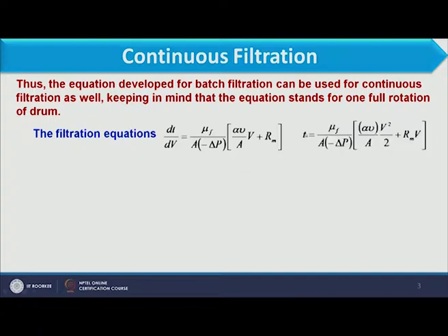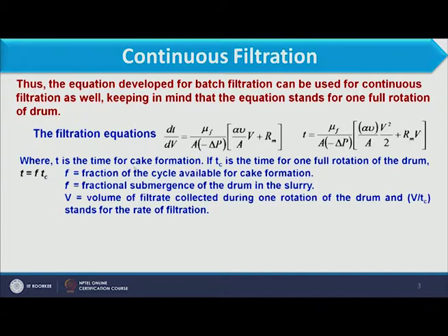When we integrate it, we get the time expression in terms of volume, where t is the time of cake formation and V is the volume collected. V is the volume of filtrate, so in whatever time filtrate is collected, in the same time cake formation is carried out.